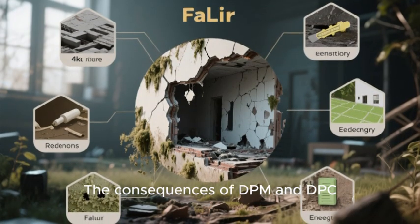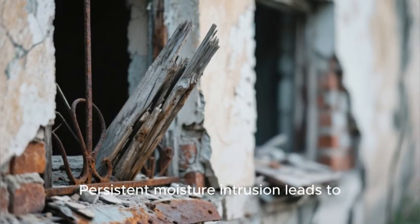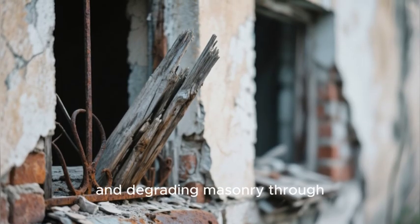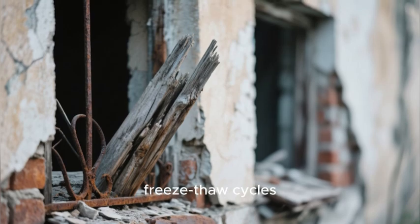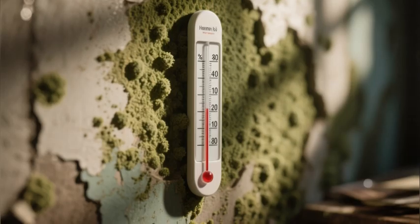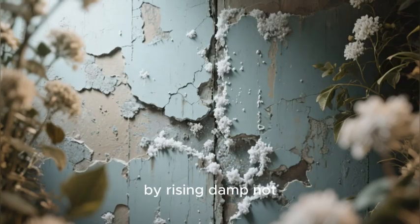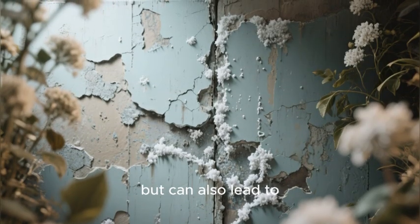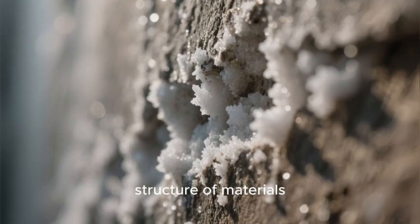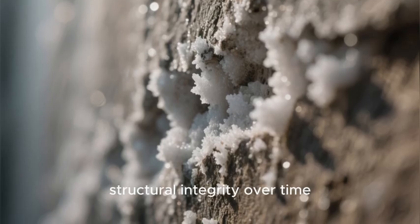The consequences of DPM and DPC failures extend far beyond cosmetic concerns. Persistent moisture intrusion leads to deterioration of building materials, corroding metal fasteners, rotting wood elements, and degrading masonry through freeze-thaw cycles. The elevated moisture levels create ideal conditions for mold growth, which poses significant health risks to occupants through poor indoor air quality. The soluble salts carried by rising damp not only cause visual damage but can also lead to efflorescence and cryptofluorescence, where salt crystallization within the pore structure of materials creates internal pressures that can spall surfaces and reduce structural integrity over time.